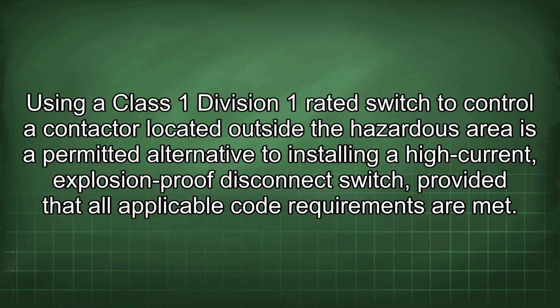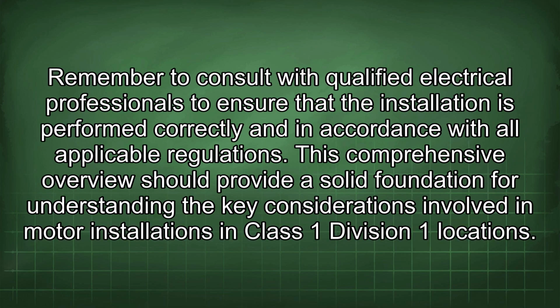Using a Class 1 Division 1 rated switch to control a contactor located outside the hazardous area is a permitted alternative to installing a high-current, explosion-proof disconnect switch, provided that all applicable code requirements are met. Remember to consult with qualified electrical professionals to ensure that the installation is performed correctly and in accordance with all applicable regulations.